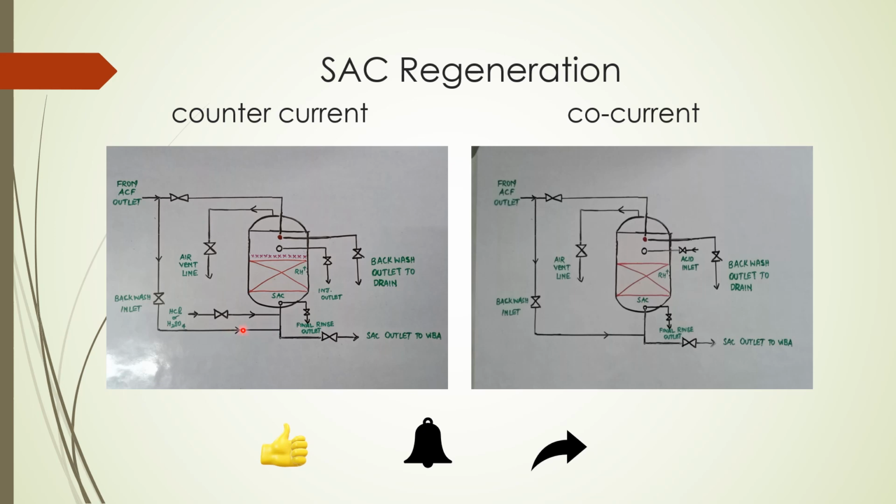But once in 5 or once in 7 regenerations, we have to give backwash. So during that time, when backwash is given, that means the inert resin over the bed normally will not get regenerated during acid injection. Acid is kept as inert, and downflow water is also always coming. So the bed volume below this inert resin only will get regenerated.